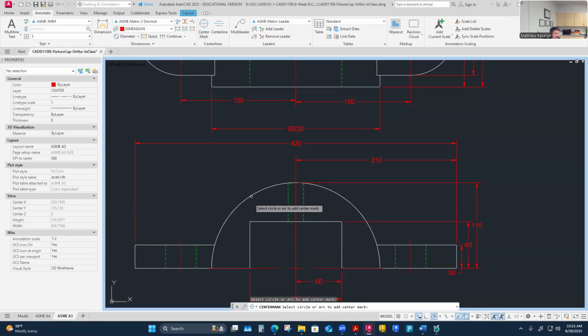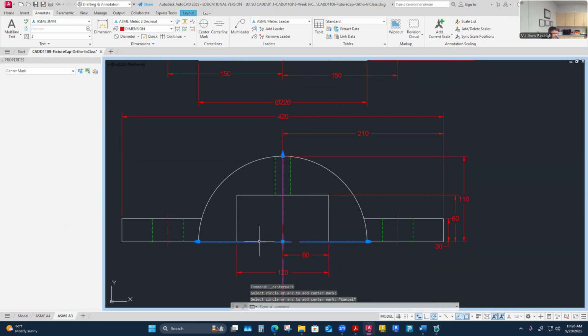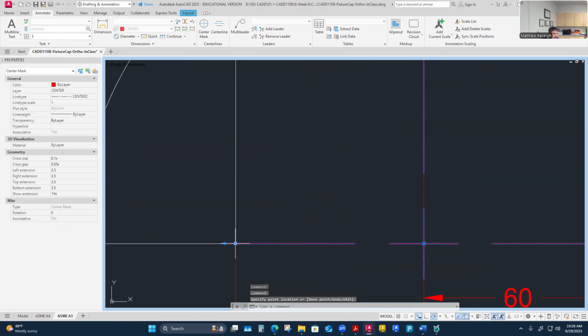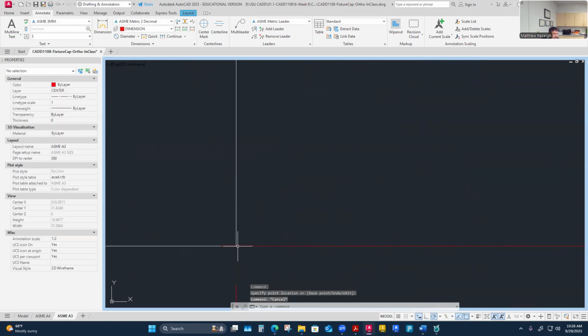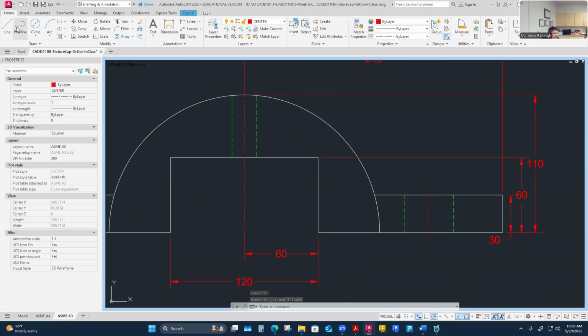Because you would add it here, but then what I would do is go through and tuck this one up. So this one's going to become the line I have, and then I would modify these ones to be about a 16th away from this, with no extension. I wouldn't want them to overlap. I think we did that in one other drawing where I pulled it away a 16th and then turned off the extension. What it would pick up that I don't have here is a little bit of a horizontal center mark. So I could add that even without making a center mark.